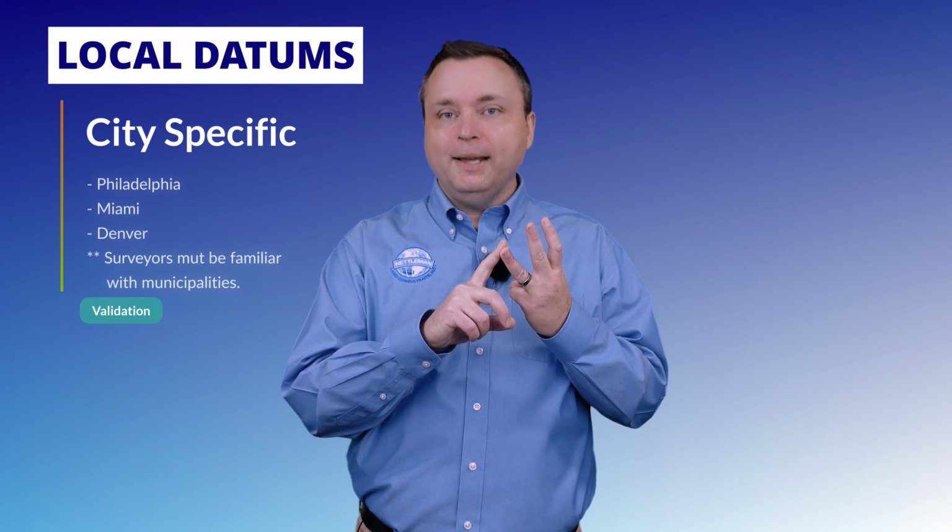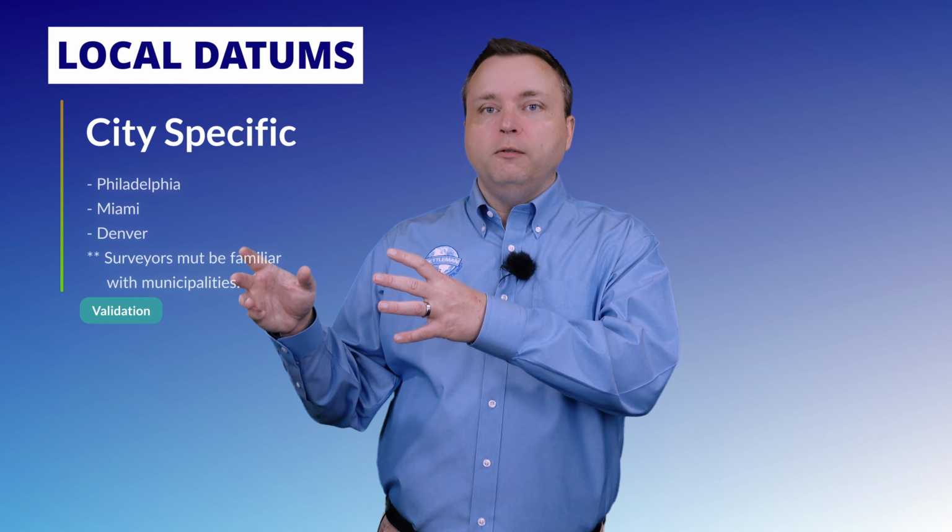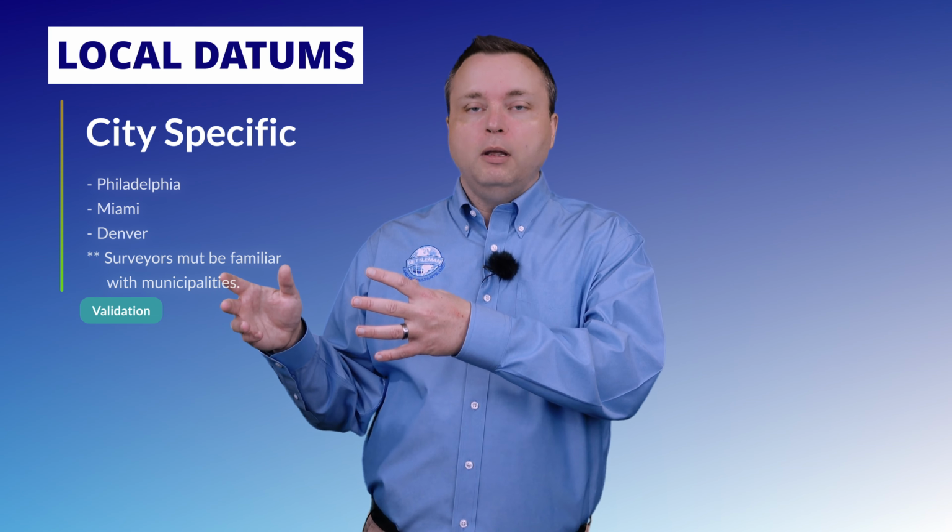Now, the last topic here is about local datums. The city of Philadelphia made their own datum. The city of Miami made their own datum. The city of Denver, Colorado has its own datum. And if you are a surveyor not from that area and not familiar with these local datums, it can be extremely dangerous, because what if the engineer is using the local datum, but you are using the federal national datum, one of them? Well, you could be off by tenths of a foot all the way to tens of feet. And that's really scary.